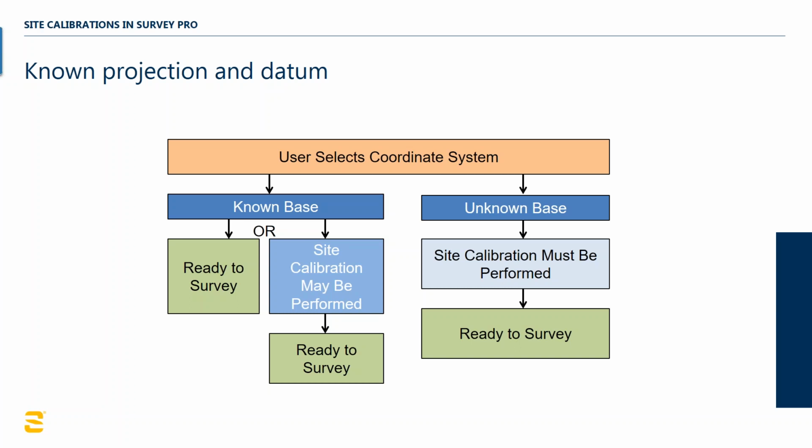In the second example, that's very much like a resection scenario. Hey, I put my instrument somewhere that is unknown, so I must hit some control in order to get close. And in that case, you'd be looking at like a 5 to 10 meter adjustment, because that's the precision of a standalone GPS base when you just set your own base on a new point.